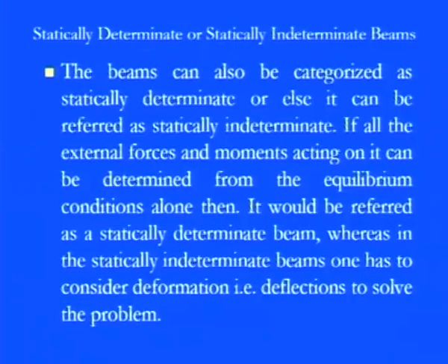So now you have the two main forms of beams, based on what kind of supports are there, and that's why you see we are classifying accordingly. One, we have a cantilever beam in which one end is rigidly supported, nothing can happen in terms of translation or rotation, and one end is absolutely free. So we can apply any kind of moment, point load, or concentrated load like that.